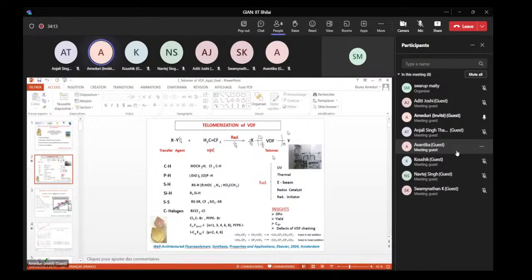the monomers. Usually when you have a double bond, you have a pi and sigma bond, and the pi bond is open while the sigma bond remains. Telomers usually are low molecular weight polymers, but they are functionalized, and the n can range between 1 and, let's say, 50. So it's very difficult, because of the presence of a chain transfer agent, to go to very high molecular weight.